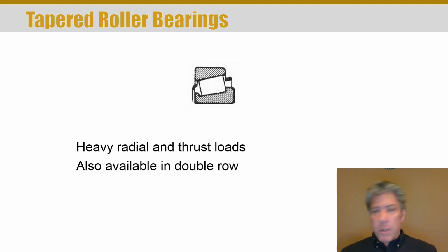As a matter of fact, a friend of mine that was an engineer told me once that you can't make the rolling elements and the raceways too smooth. If you do, what will happen is there will be sliding in the bearing as it operates, and rather than all of the elements sharing the load equally and being stressed and relieved, it'll slide, just one area of the element will wear, and the bearing will fail prematurely. So you actually have to control the surface roughness but not make it too smooth, which was interesting. I had never thought of that.